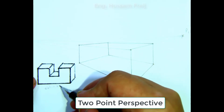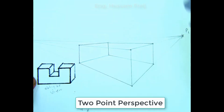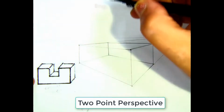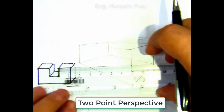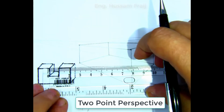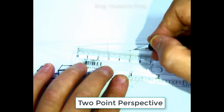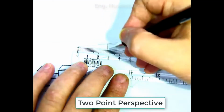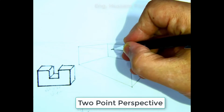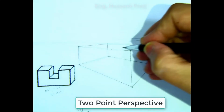Oblique view, because here I have 45-degree angles. Okay, so I want to draw it in perspective view. How to start? Okay, you have to start with assumption or measuring like this. You have to say, as an example, here 1, 1, 1, so distance 1, 1, 1. Okay, here they have 5. So you have to try to decide how to divide it. I would suggest you divide it into 3 pieces without even measuring, like this.